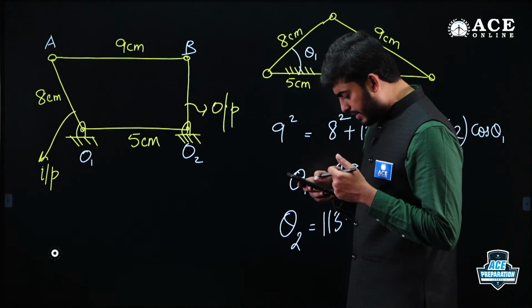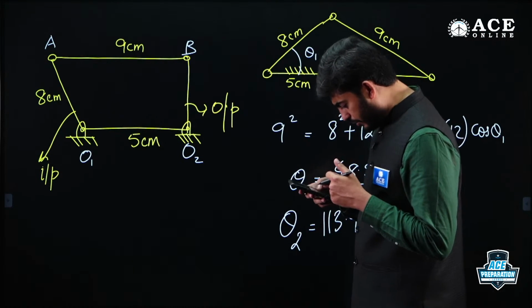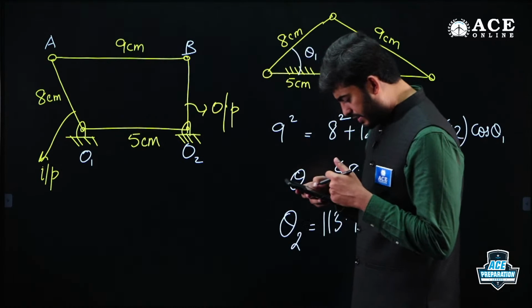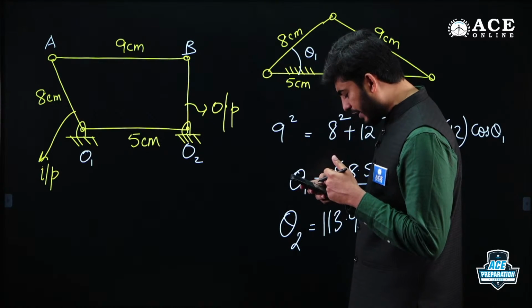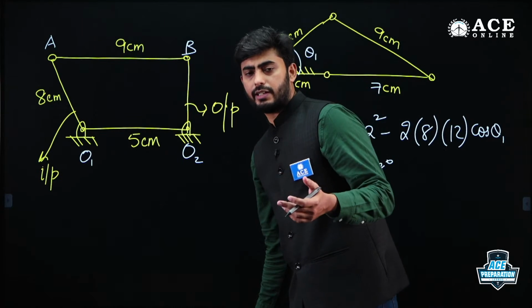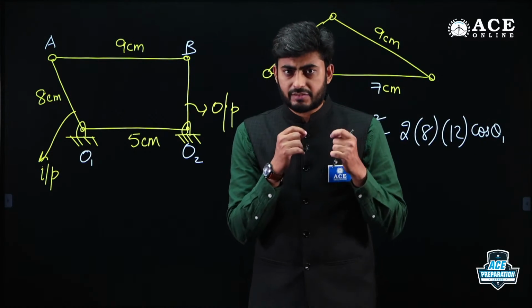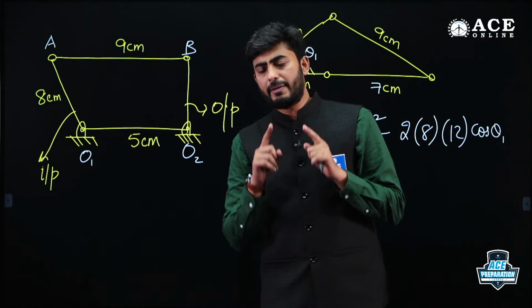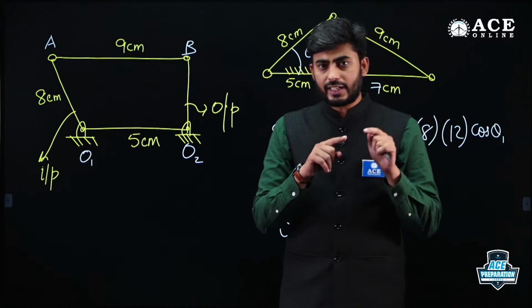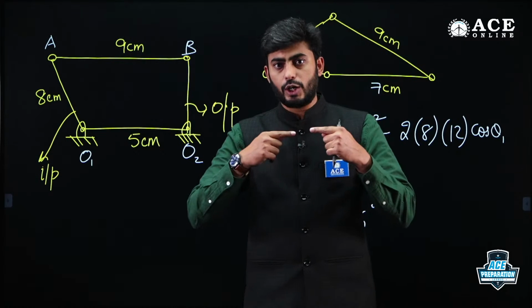Priyansh, I guess I was supposed to answer your question: how to visualize these diagrams for calculation in the crank rocker mechanism. In order to determine the extreme positions of the rocker, you make the crank and the connecting rod, or coupler link, collinear.